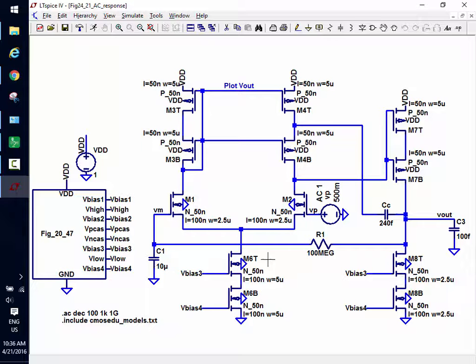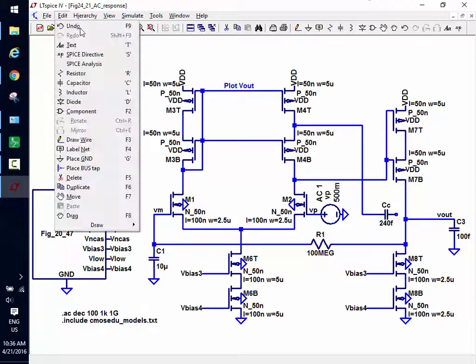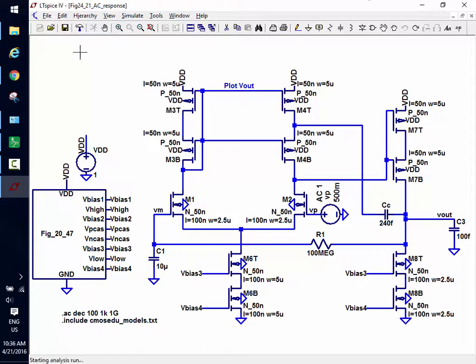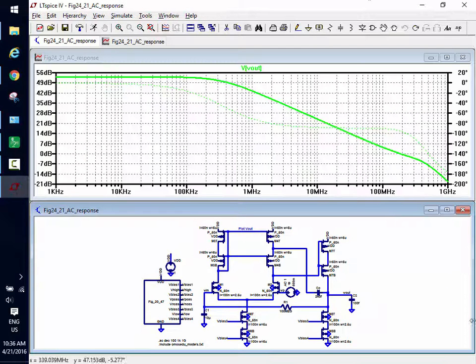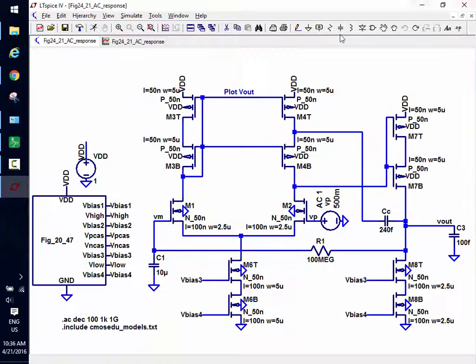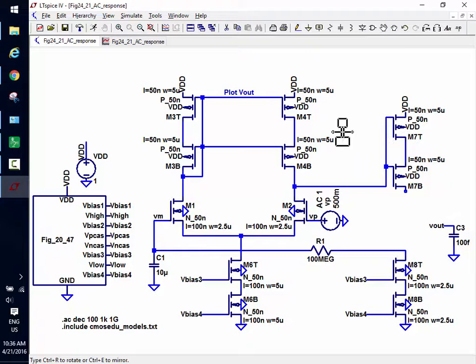It may not work because it's really limited output swing because you've got the NMOS on the top and the PMOS on the bottom. But let's do it and see what happens if I add the buffer to this schematic. Or actually, let's run the sim first. Looking good. Then let's get the scissors out. And then let's move this to here.